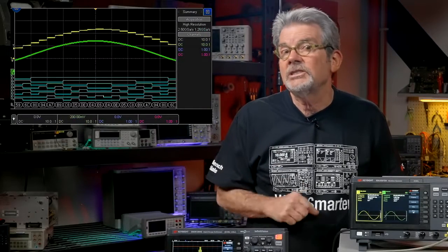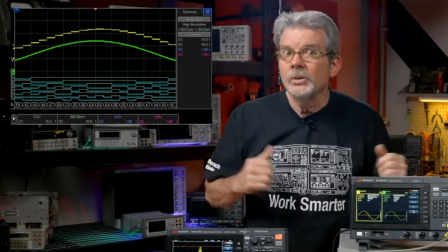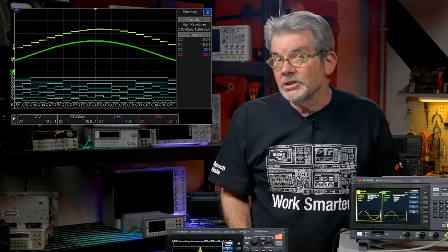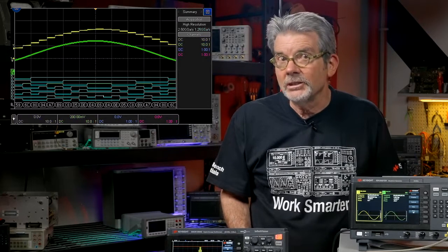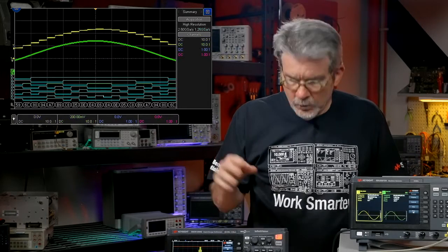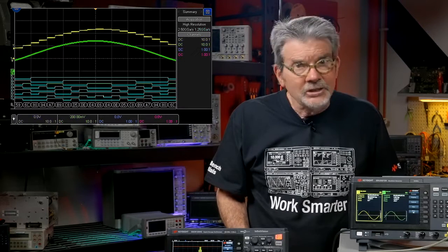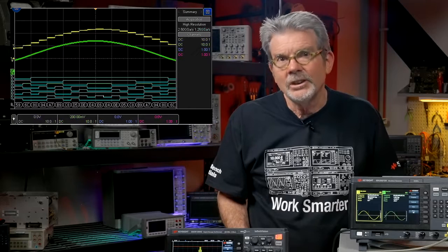I should also mention there's another class of oscilloscope called a mixed signal oscilloscope, or MSO, that adds 8 to 16 digital channels of acquisition. That means that these additional 8 to 16 channels can only show if the signal is above or below a threshold setting. This graphic on your screen now shows an oscilloscope's display with both analog channels and digital channels turned on. The waveforms at the bottom of the screen are from the digital inputs. MSOs can be very handy if 4 analog channels aren't enough.